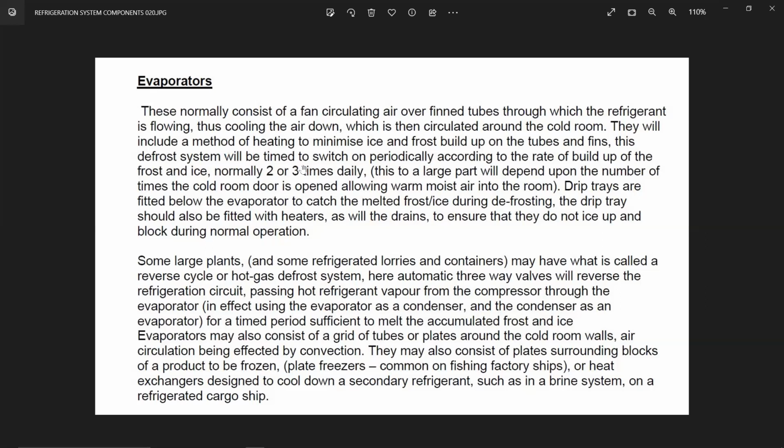तो अगर वो water वहाँ पे रह के क्या होता है, water will basically start icing up over there, and then slowly the entire evaporator will basically get iced up. And when the evaporator gets iced up, then obviously your heat exchange will basically suffer from it.